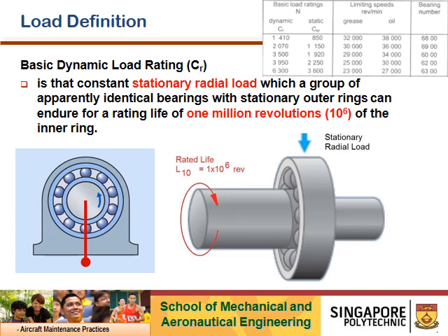That means you will go to your appendix bearing catalog, you will see there is a basic load rating in Newtons, a CR. So when a particular manufacturer manufactures, for example, a 6800 bearing number, I hope you remember what the 00 refers to. Remember the 00, 01, 02, 03. They are supposed to read directly on the chart what the ball diameter is. So 00 will be, I can't remember, you can also refer. Okay, for the 6800 particular bearing, they applied a CR of 1410.